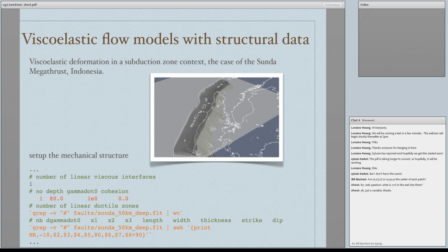And then, second, there are some residuals in the far field, but much smaller, and they are due to fast Fourier transforms that assume symmetry of the displacement field. That is not a desirable property, but we cannot do without it. So it introduces some very slight residuals in the far field. The solution for that is to make your mesh larger and larger. That demands more and more computational resources, but if you have access to that, then that's not a problem.